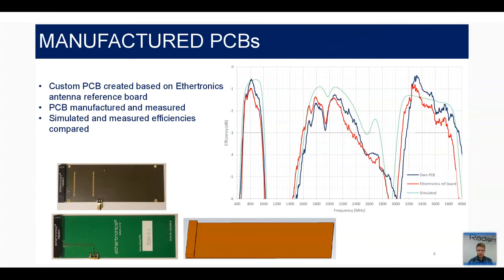First we measured our custom PCB and the reference PCB just to make sure that everything was okay in our antenna layout. From the measurement results, we can see that both measured curves are pretty much the same, so no major differences there. So the antenna was okay. The simulation results are also shown there, and the simulation follows the measurements quite nicely. The efficiency is a little bit more optimistic in the simulation results, but that is pretty expected.